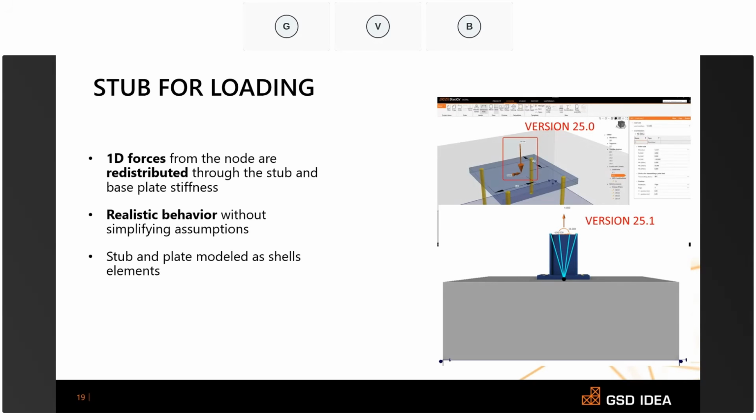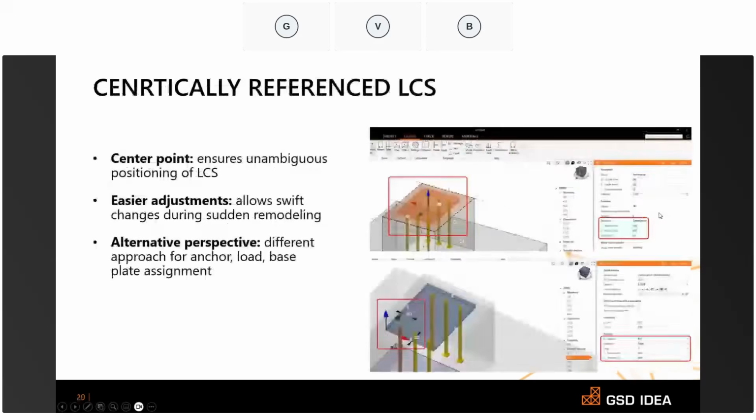And also, the stub and the plate both are modeled as shell elements so that the load transfer behaves exactly as in real engineering practice, very similar to how it works in the connection application, but now directly in the 3D detail application.